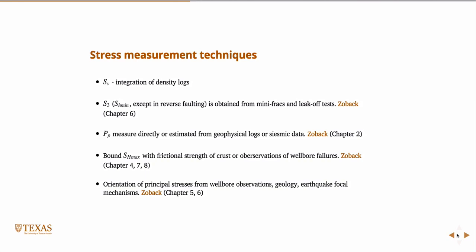So I think we've already talked a little bit about this, but in terms of a couple of them, how we measure stress in the earth. But really this is a preview of things to come in terms of what we're going to talk about in more detail. The first one we've already talked about, though. So the vertical stress we can get from the integration of density logs, or just flat out estimating 1 psi per foot.